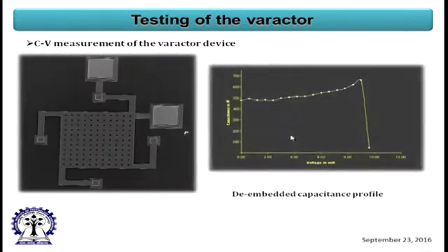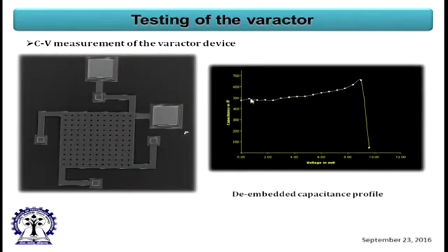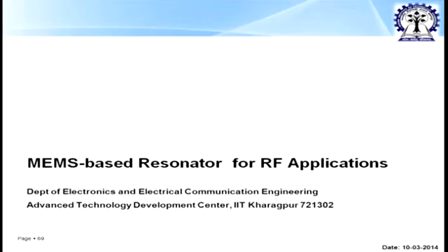Then if you calculate and de-embed that, you can find a beautiful change in the capacitance, because it is only the change in capacitance coming from your device, which is from 500 femtofarad to 650 or 620 femtofarad. That is the requirement imposed on your design. So, what you find is the capacitance after de-embedding, which gives you a much more realistic design and realistic capacitance.